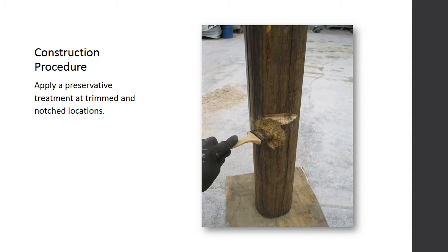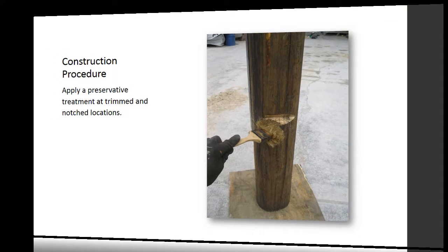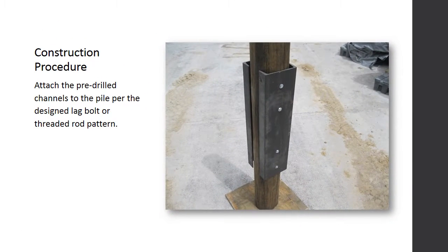Where the pile has been trimmed and notched, apply a preservative treatment to help protect the pile going forward. Finally, attach the pre-drilled channels to the pile per the designed lag bolt or threaded rod pattern.